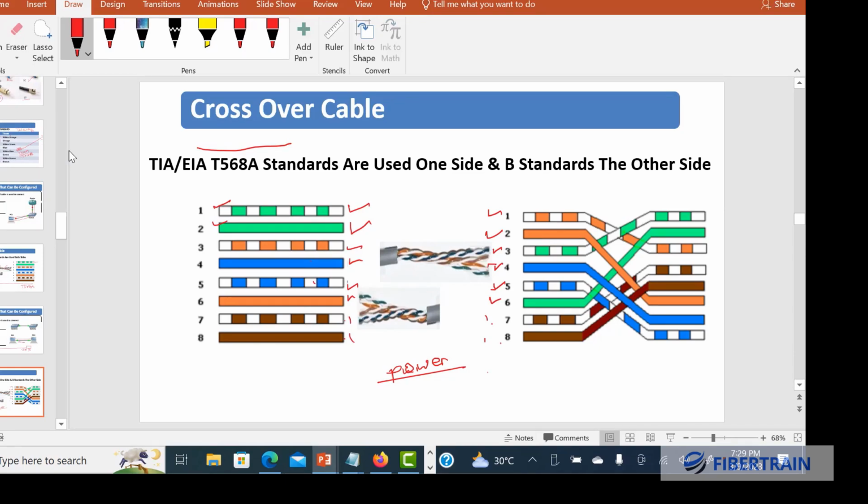Okay, you know that these category cables can be used to connect CCTV cameras, right? Yes. Those are IP cameras. So where the cameras are mounted, what gives them power so that they power on? This same cable can supply them both signal and power. So the cable can give the camera internet so that the owner of the shopping mall could be viewing the mall in his home. Yeah. But apart from supplying internet to the camera, it will also supply electrical power to power it on. So we don't need to get an electrician to come here and put a socket for the camera to connect to. So these network cables can carry both network signals and power.